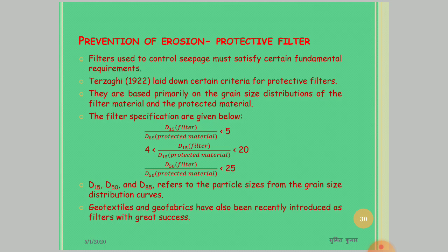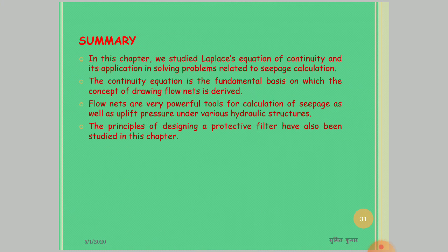Geotextiles and geofabrics have also been recently introduced as filters with great success. So, in this chapter, we studied the Laplace equation of continuity and its application in solving problems related to seepage calculation. The continuity equation is the fundamental basis on which the concept of drawing flow nets is derived. Flow nets are very powerful tools for calculation of seepage as well as uplift pressure under various hydraulic structures. The principle of designing a protective filter has also been studied in this chapter.